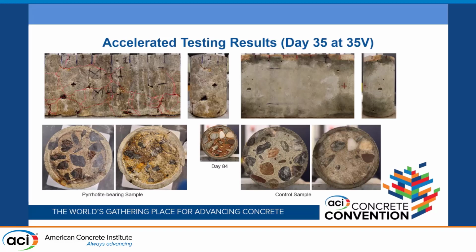For the sodium chloride end, you can see signs of oxidation. And on the sodium hydroxide end, you can see the matrix being eaten away. One of the reasons why this might be happening is that when iron sulfide oxidizes, sulfate is released into the concrete. Hydrogen is also released, sulfuric acid basically, so protons and sulfates are released into the concrete.